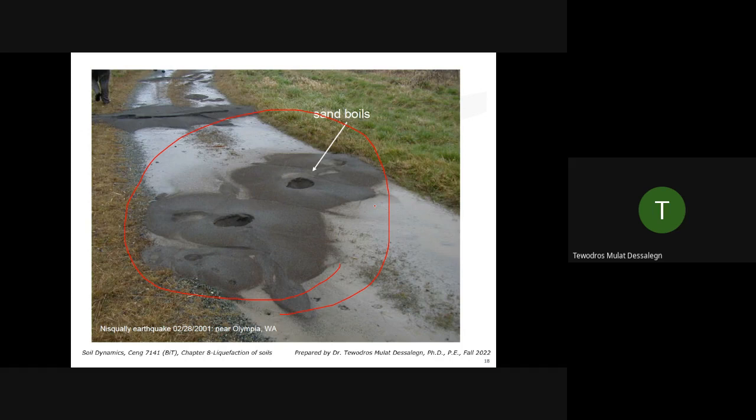If the ground is a loose deposit site, we expect this. We don't expect this if the ground is a dense deposit, or a high plastic clay, or very gravelly soil. If it's gravelly soil, the water will have enough time to go from one place to the other, so it doesn't carry too much pressure to cause liquefaction.